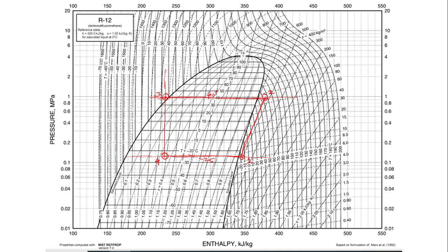Okay. So whenever the superheating and subcooling is given, please take care that both the processes take place at constant pressure only. You just have to add or subtract the degree of superheat and the degree of subcooling respectively from the evaporator and condenser temperatures. Fine. So this is what the point number 1, 2, 3, 4.